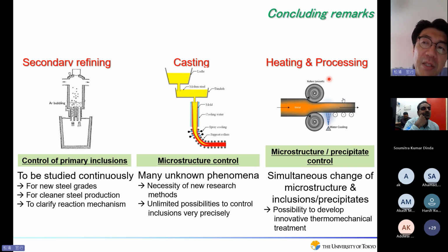But in other words, some elements might be entrapped again within the steel products and may contaminate the molten steel again. So it depends on the steel grade. But one important point is that you can modify the oxide inclusions, for example, or reduce the gas elements in the steel material, if you choose the proper slag composition.